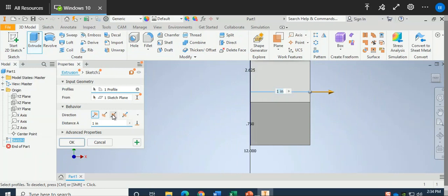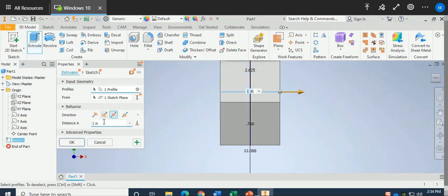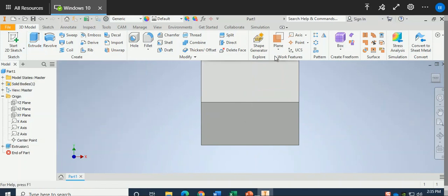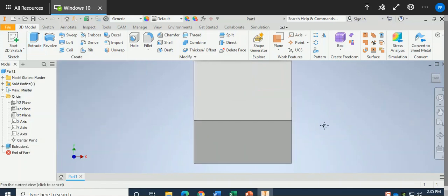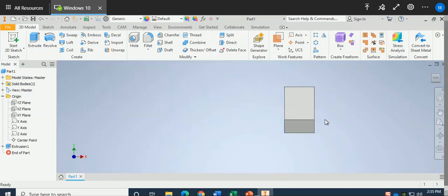And I'm selecting the extrude command, okay? For the extrusion, I'm choosing two-way extrusion, and I am changing the size from the default 1 inch to 1.625, 1 5/8 of an inch. I'm typing 1.625 extrusion, okay? And enter.